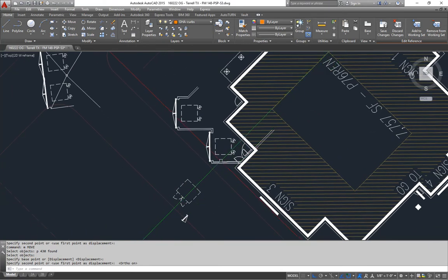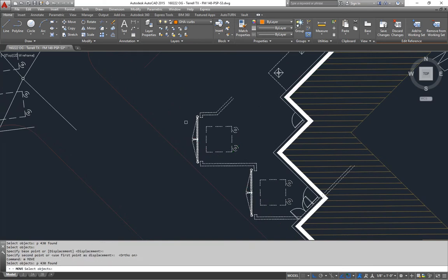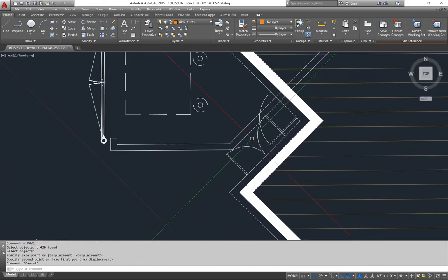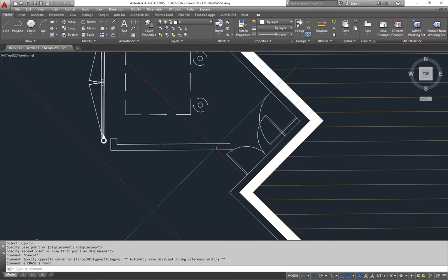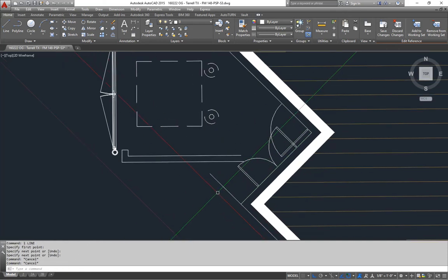Woo, this is tight. It's a tight fit, guys. Let's push this out a little bit. I think we might be able to make this work. I keep all this stuff on the 0 layer, so I'm going to get on the 0 layer and draw this off of there. I'm going to set my offset distance the same as that, offset that far, fillet radius 0.